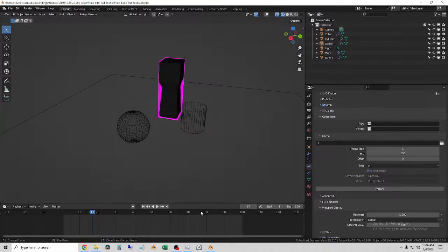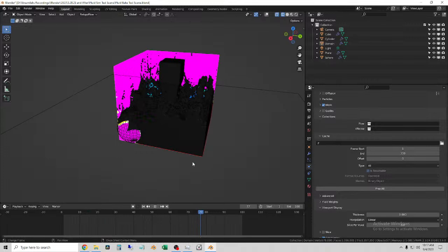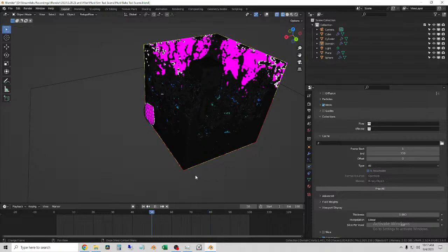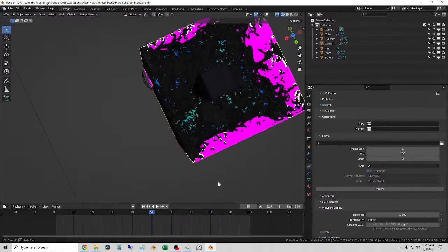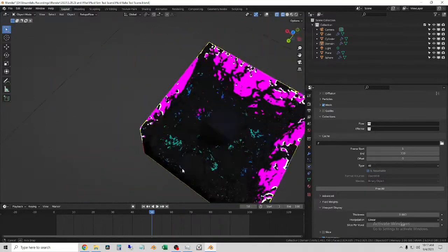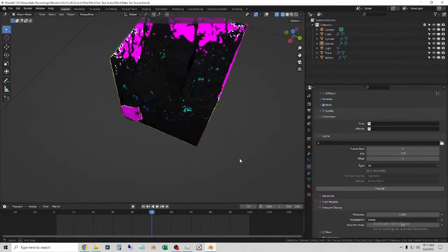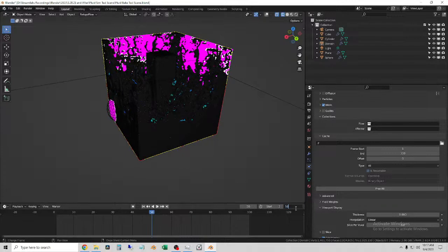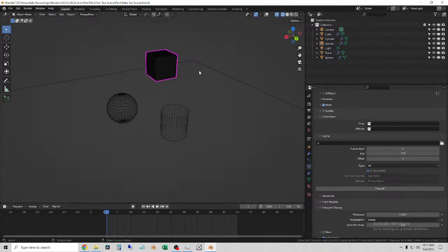Okay. Yeah, so we want our effectors, which are the objects in the scene. We want those to be in the water. Otherwise, they didn't do anything. So let's make sure that 50 frames gets us some interaction. Yeah, 50 frames should give us plenty. Sweet. All right. So yeah, let's do that. So we're going to end our simulation at 50 frames instead of 100. I'm going to set this back to the first frame.